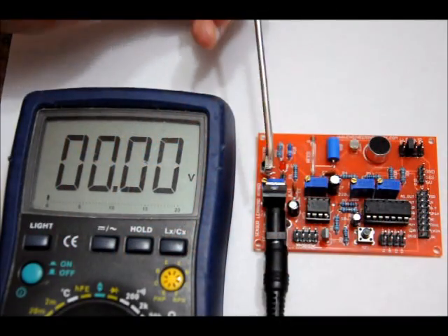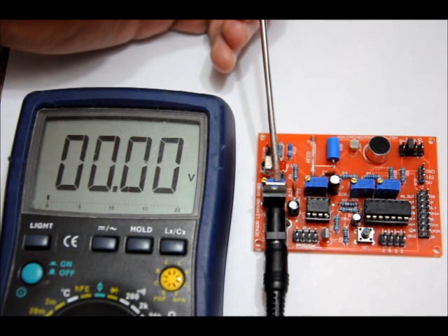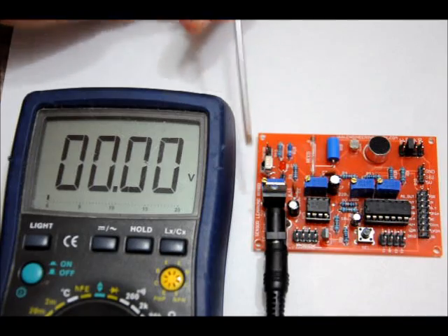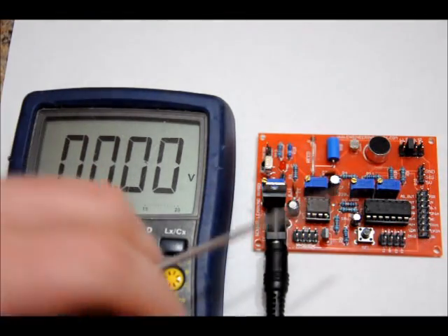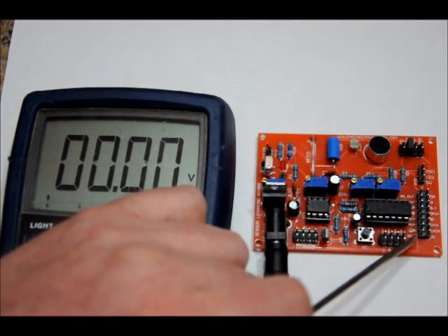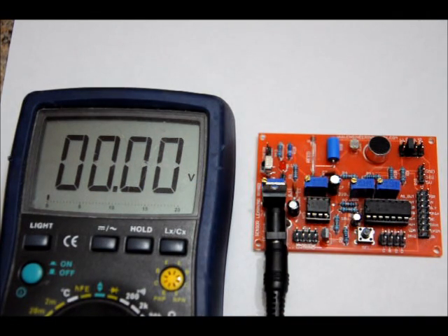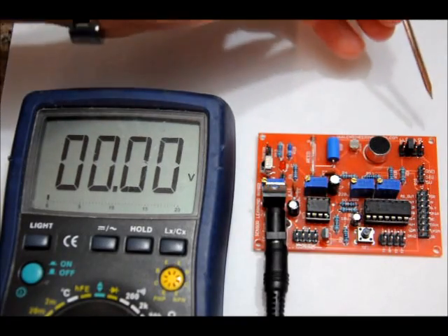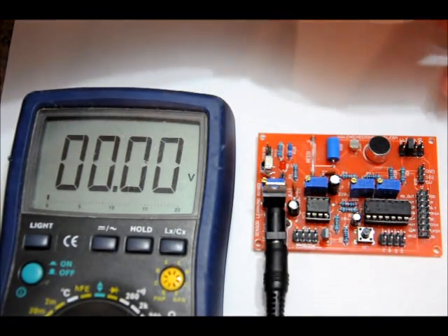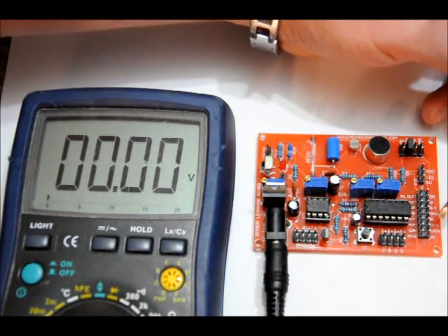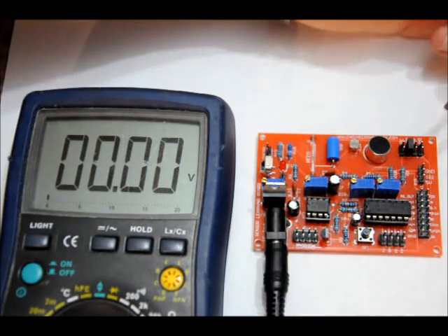Things to remember: our VAR variable resistor is right here. Turn the voltage up by turning the little spring clip clockwise. To turn the voltage down, turn it counterclockwise. And the VAR pin on the main pin block is on the lower left, second from the bottom, labeled VAR. Our div1 pin from the light dependent resistor circuit is right here, lower right, third from the bottom, labeled div1.